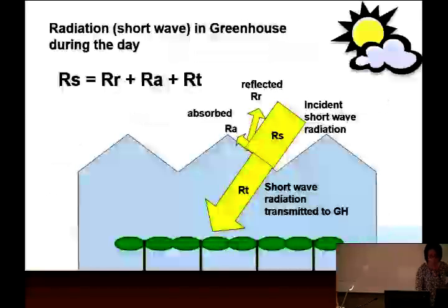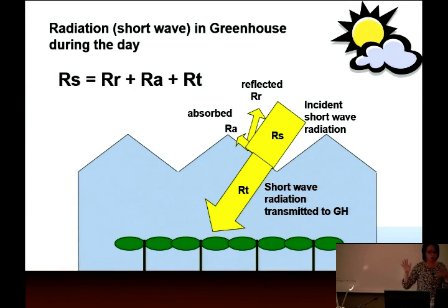All right. Okay, so greenhouse energy source, obviously, solar radiation. And greenhouse is designed to capture the solar radiation in two ways: for photosynthesis, we talked about Monday, and also thermal, so that warming up, increasing temperature. In an arid environment like this, increasing temperature is appreciated only for a certain period of time. Even in winter time, we need to reject the heat, otherwise it gets too high inside the greenhouse.